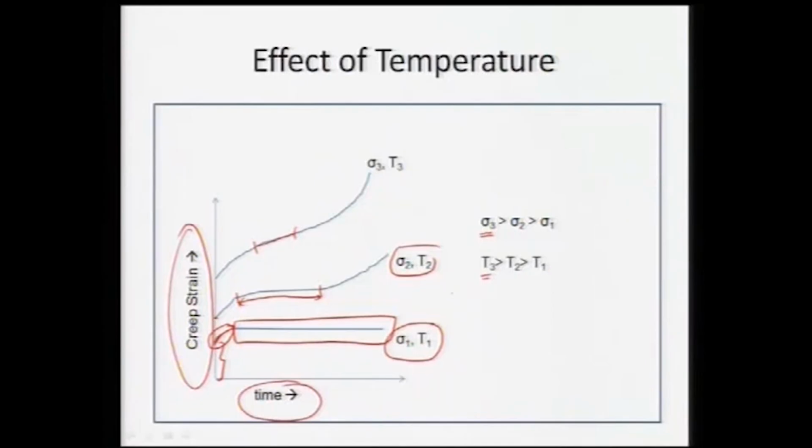Also the damage is now to a very large extent, because the third stage has started very quickly. In this case the third stage has not started yet. In this case it has started at this particular time, whereas in this case it has started much earlier. So, that will lead to very rapid failure of the component. So, as we have a very high stress level or very high temperature, that will lead to eventual failure at a much more rapid rate.